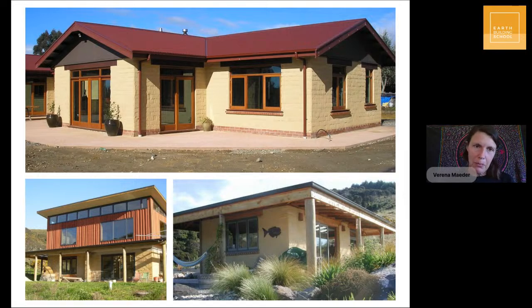I've put in a couple of images here. They're bigger buildings. The bottom right one is a small house, a 30 square meter building, but I just wanted to show you what I'm talking about. The top one has that gable end with a timber situation that hangs over the mud brick a little bit and has a flashing so that water can drip off. These people designed with minimal roof overhangs. Their bricks were very good quality. So this building has done really well, even though there are minimal roof overhangs.